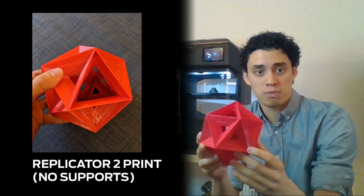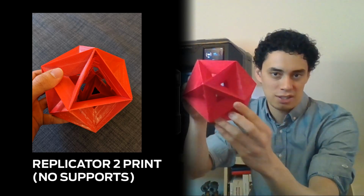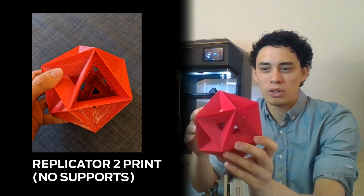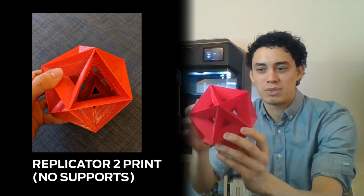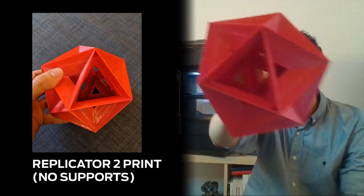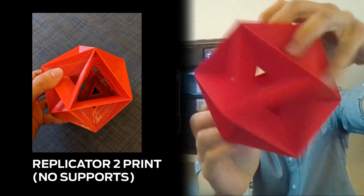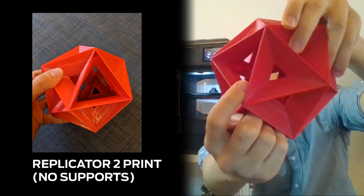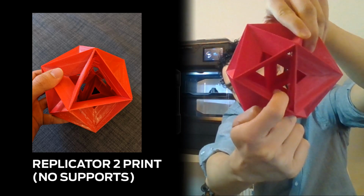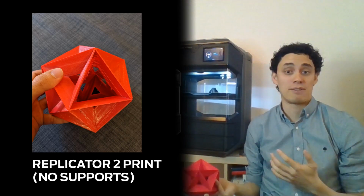The Rep 2 was the first MakerBot printer that I had. It's a fairly intricate part, which is why I didn't want to use supports, and I wanted to create something that was self-supported. So I had to accept that at some point, you can see it here, and you can probably also see it on the photo. Where is it? Here, right? Some of these unsupported areas would have these overhangs that prevented the filament from attaching properly because I didn't have supports, right?